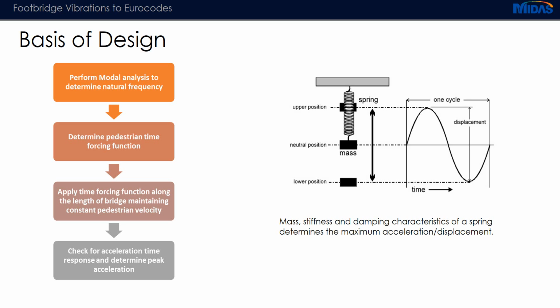So whether the footbridge is sufficient to withstand the vibrations, in terms of the comfort of the pedestrians. So our ultimate goal is to basically check the acceleration of the bridge when the pedestrians are walking or jogging on it, or when there is a crowd condition. So in order to calculate that peak acceleration, we need to carry out a dynamic analysis.